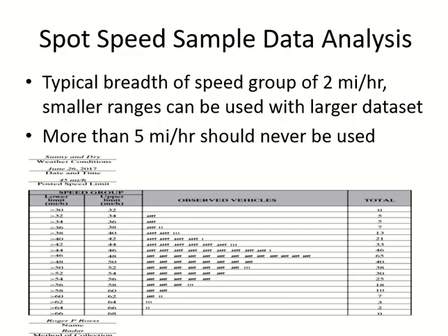The minimum depends upon the number of values you have and the distribution of the speed. If you make a group which is too big, say a group of 4 miles per hour, now all your values fit into one group. So 32 to 34, or 32 to 36, all values are in this group. That means you did not distribute the data properly. You should make a smaller group so you can have more groups. 1 group, 2 groups, 3 groups are considered a very small number. So ideally you want more than 3 groups at least.